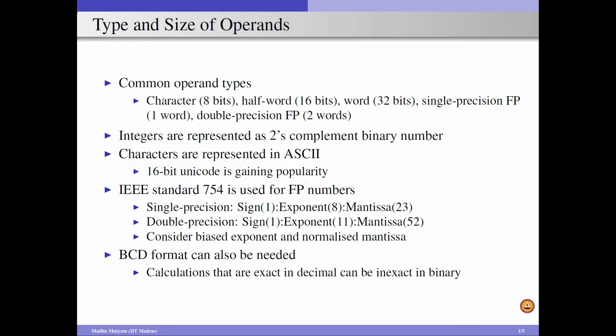And sometimes it may not be possible to perform exact calculations using binary numbers. So, in those cases, especially financial calculations and so on, where the calculations need to be performed on decimal numbers, to support those things, we can consider the BCD, binary coded decimal form.